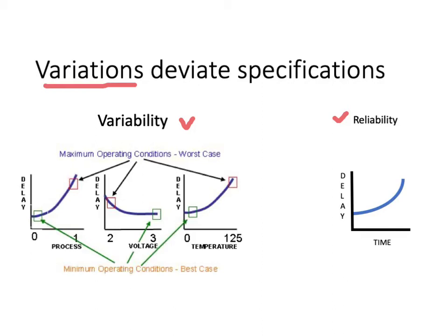metals, the geometrical shapes itself of the metal layers and the transistors themselves cannot be exactly reproduced between die to die, and also within a single die itself. If you have two adjacent transistors versus two transistors that are further apart on the same die, that is the same integrated circuit, you might even have some variability in that, right? The transistor gate length will not be exactly the same, even though you have specified in the front-end design that they're exactly at the same technology process, which means that in theory the gate lengths should be the same, but they're not, due to process variations.